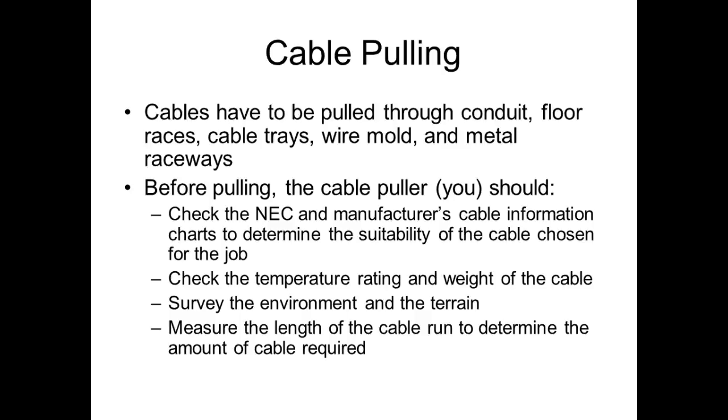We had to pull that sucker back out and then pull it back in. But what we did is we stagger spliced it, because you didn't want them on top of each other, and then tape them up. But you really wouldn't have to tape them up because they were stagger spliced and they were underground. So that was a fun job.